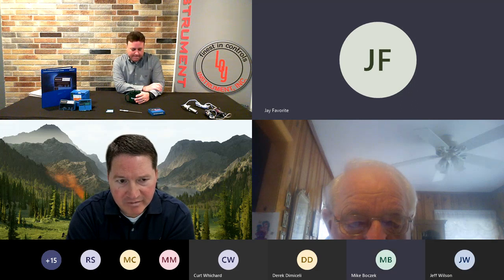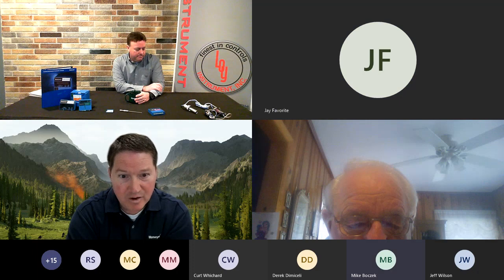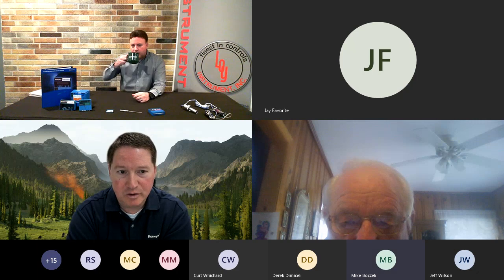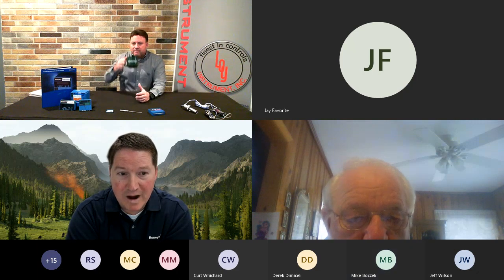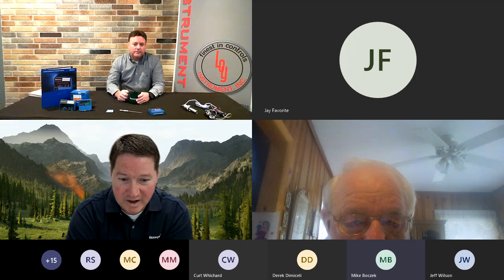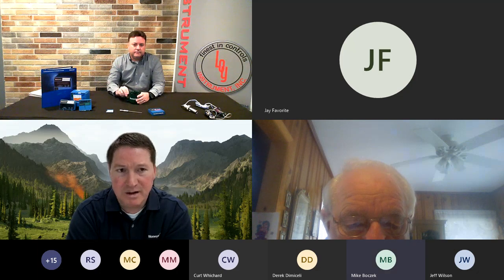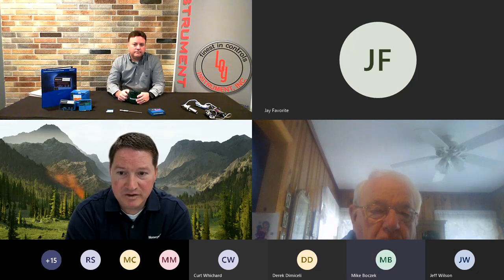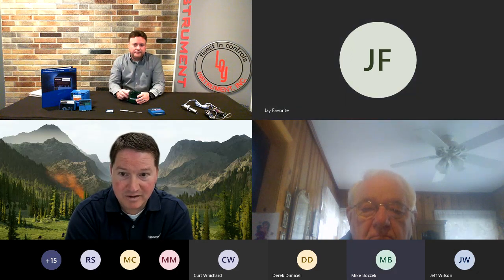Hey, Jeff, just a quick adder to what those guys were just asking about. There are occasions when you may have, let's say it's a refractory block, and there's not enough ground surface where you can't get a 4-to-1 ground surface where you've got a good metal, solid earth ground back to the burner. If you're using refractory, that's not an uncommon problem. And to answer your question, I think that was Derek that was asking, you may need to take rods and actually tack them onto the end of the nozzle to extend out to get some actual metal from that cast burner head, the nozzle, out beyond the refractory to make contact with the ionization envelope in the flame.